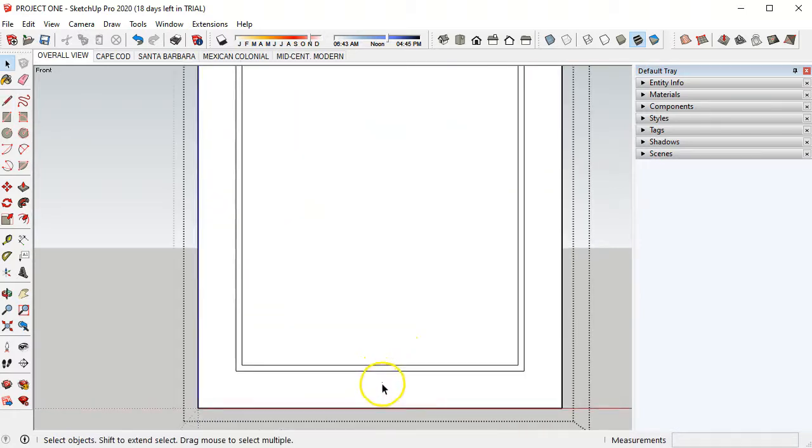If we get a little closer and we select that line, we can right click and divide. Now you'll get these little red grips, and I'm not holding my finger down on the mouse, I'm just moving the mouse left and right. When I go left, you can see that now there are 2 equal segments. If I move to the right, now there are 4, and I can keep on going 5, 6, all the way to 36, maybe 100 segments. Wow. So you don't want that. Let's say we just want something like that. Okay, and I'll show you where we're going with this.